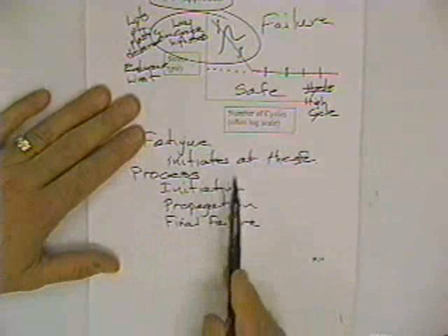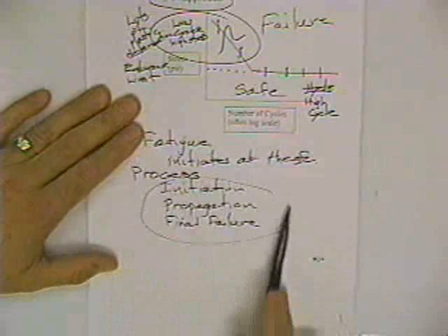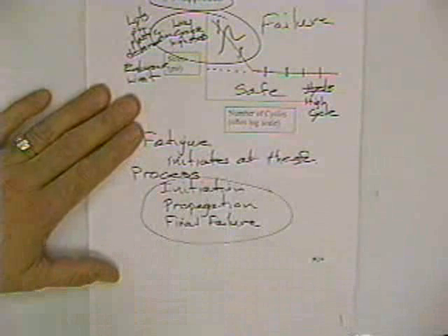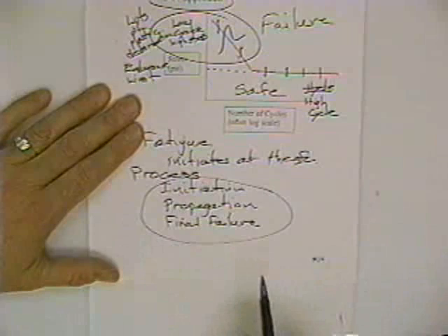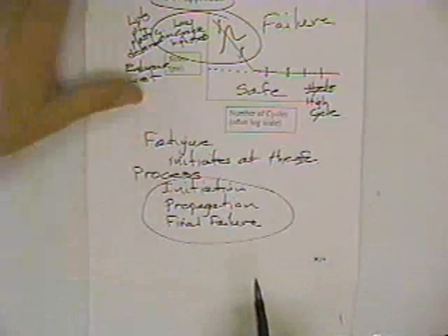And there are some techniques where you can use fracture mechanics to monitor cracks in materials, so you don't have to take something out of service because there's a crack in it. There are steam generators, airplanes, and railroads that generate electricity, fly, and move with cracks in them, but they are safe to use.